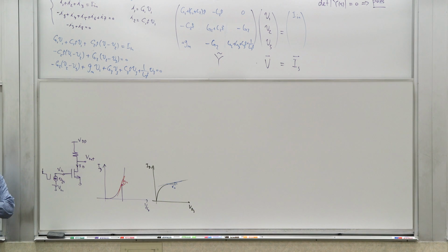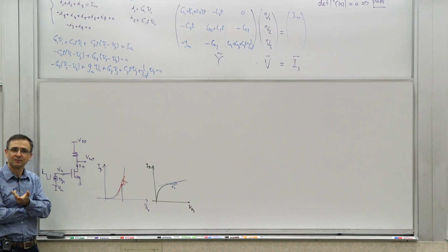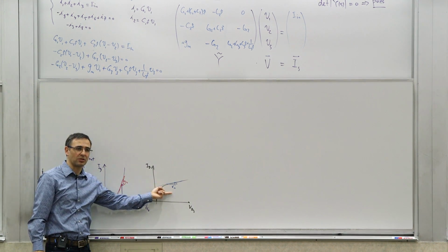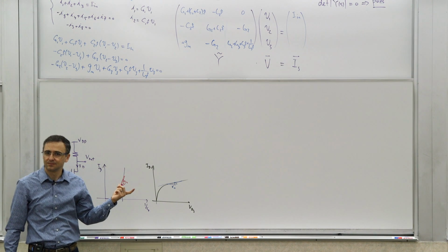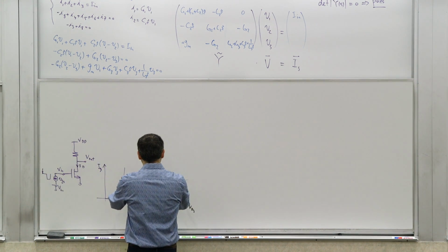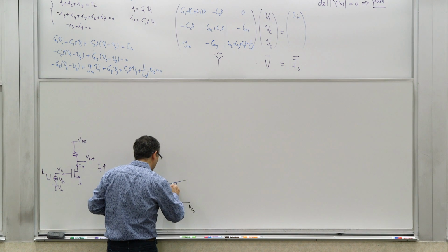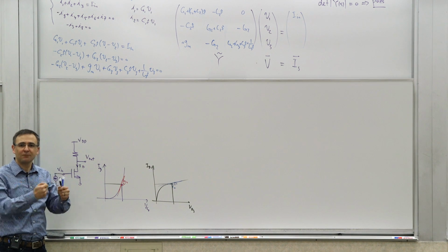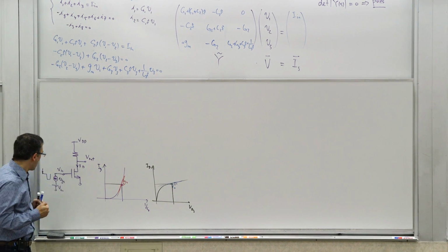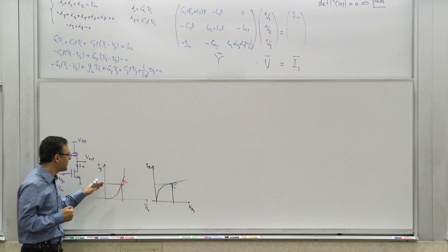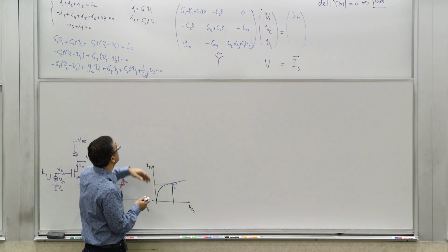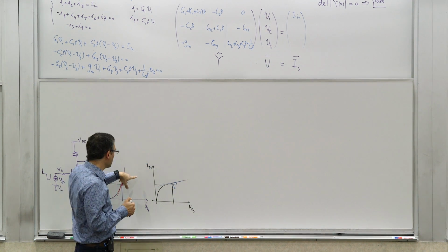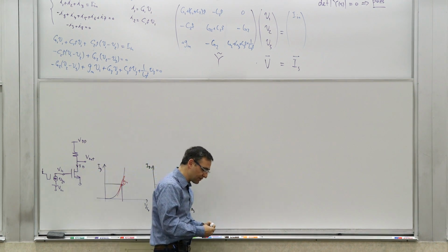So you find these parameters. From that, you develop what? You can calculate a small signal model. Right? And your small signal model is not limited to these static, low frequency parameters. You can also calculate the capacitors and all of that. So you develop a small signal model at this particular operation point that you found. Now, you use that small signal model to say, okay, if my input is changing this way, how is the output going to change? So how do we do that? We use the nodal analysis at this linearized point, right? Use the nodal analysis to estimate what the next step of the circuit is.